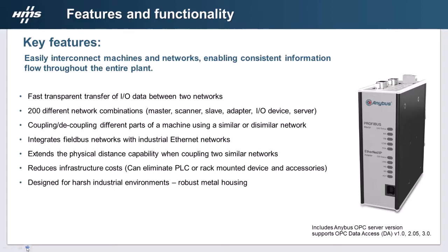It says designed for harsh industrial environments. They are in a robust metal housing, but they should be in a panel. They're IP20, so yes, it means if the installation engineer throws it on the floor, there's a very good chance it's going to survive. And as it says, provides instant connectivity. That's under certain circumstances. It doesn't require programming if it's slave-slave, just to remind you of that.